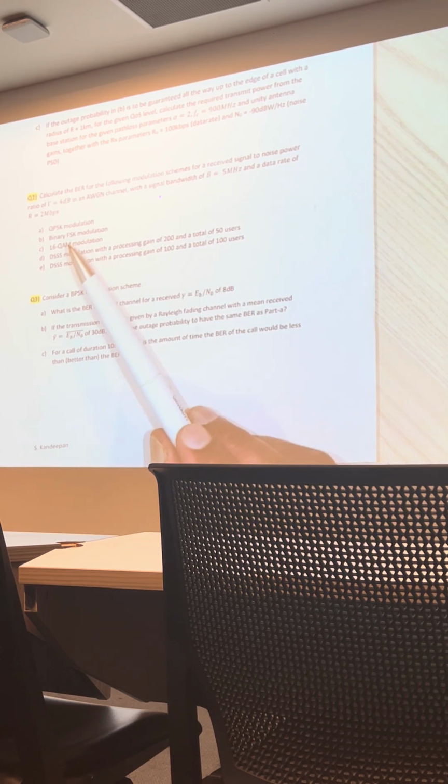So direct sequence spread spectrum basically provides unique codes or sequences to different users. All right. Therefore, it depends how many users there are to differentiate between. So if you have 2 users, the direct sequence spread spectrum will perform better than having 100 users, because you've got to differentiate between the users, and there's a self-interference factor in there. All right.